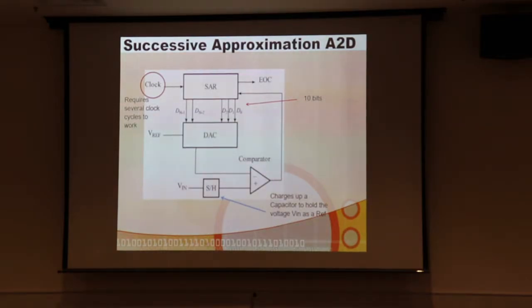So normally, to prevent that, you must filter the input. So not only do we have to put a little op amp to condition our signal, but often we need to put an input filter. And then there's some other things. We have to be careful about the output impedance of our sensor. If the output impedance of our sensor is very high, it may slow down driving current into that sampling capacitor and cause additional problems with our bandwidth. So again, that's why we want to condition it, because the output impedance of an op amp is very low.